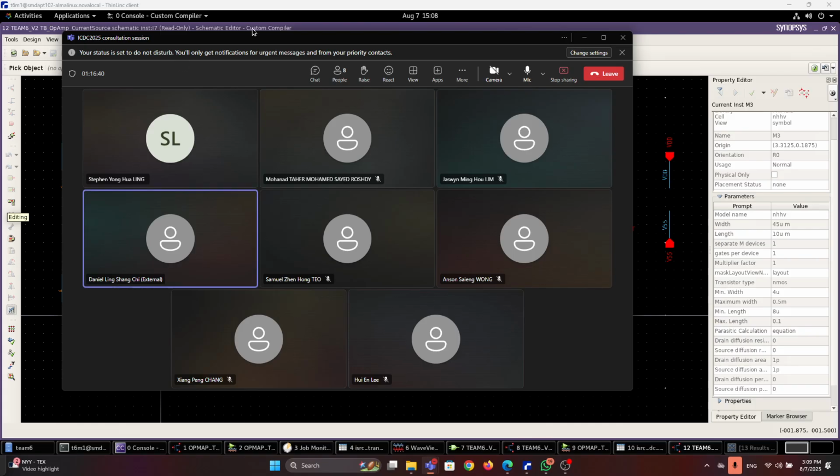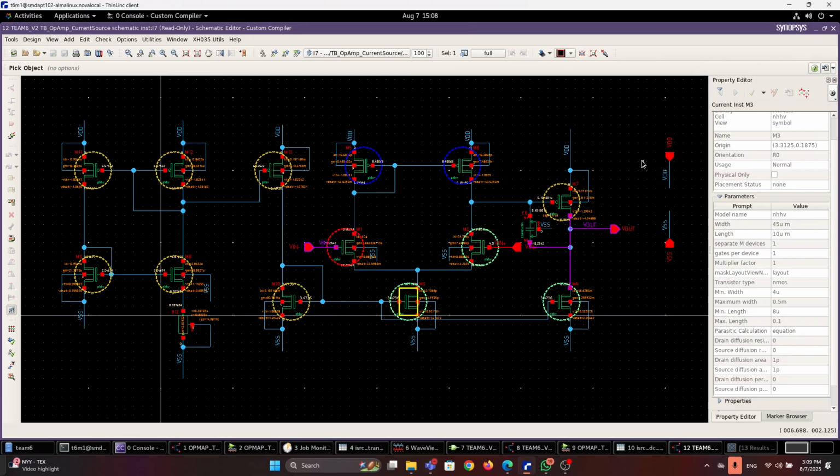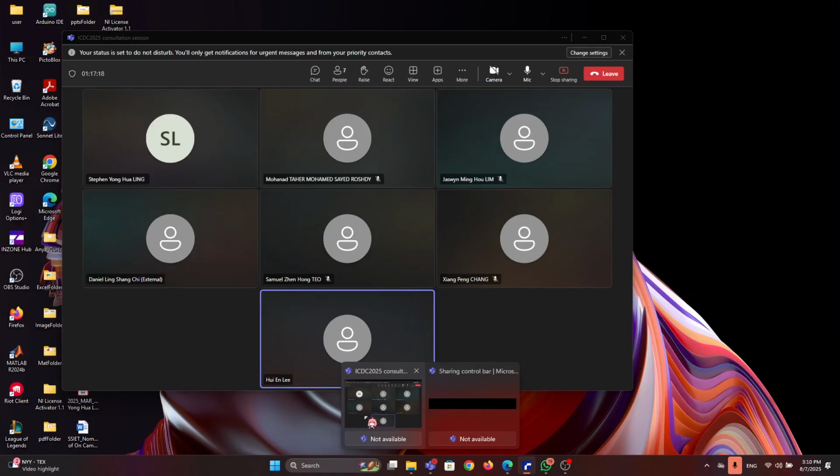Okay. Yeah. I'm still thinking a bit. Maybe Mr. Daniel, just to get some insights from you. Previously when we test the whole circuit, we supply a steady state DC voltage. We supply, I think, VDD over 2 to both gates of the op amp. And then we managed to get all the MOSFET in saturation, right?